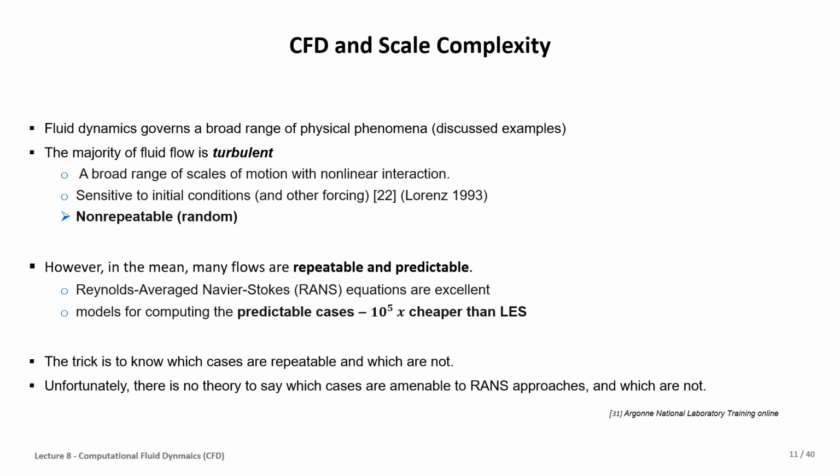Large eddy simulation provides much more accuracy than RANS. However, in large eddy simulation, we are using some filtration and we're solving the problem for a specific scale, not for all scales. Then we don't have the solution for all scales of the problem. The next one is the direct numerical simulation. It's called DNS. DNS solves the problem in the whole scale, and it's an exact and high accuracy solution.